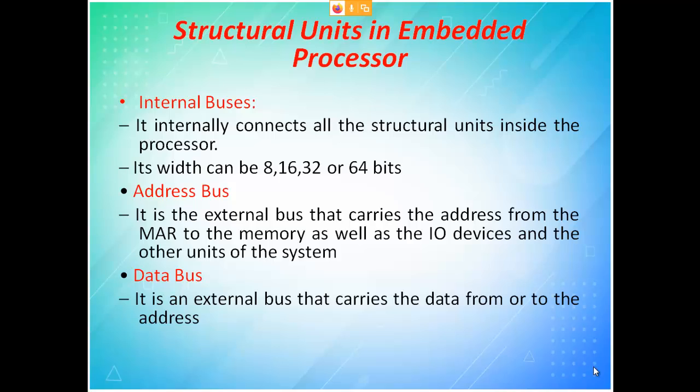Parallel is the fastest way of communicating compared to serial, but it has some drawback. When you want to communicate from one system to another system and you go for parallel, then you have to run so many wires, and that is not that easy. Even if you take 8-bit, 16-bit, 32-bit and 64-bit, practically speaking it is a little bit difficult. So between systems we will go only for serial communication,